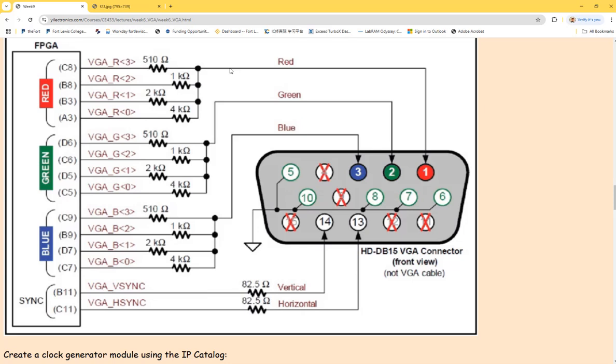You got 3 parallel resistors, right? Very important, let me tell you. 100, 1K, 2K. So what's the overall parallel resistance? 100, 1K, 2K in parallel will be less than 100, right? It will be less than the smallest resistor. So in that case, if you have this in parallel, it will be less than 500, probably like 300 something ohms.